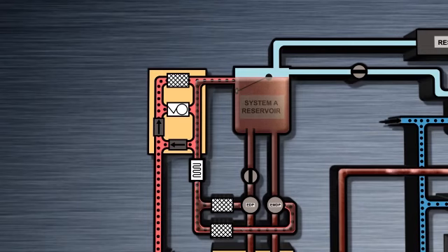Note that there are no overheat lights for the engine-driven pumps. This is because overheat situations are much less of an issue for the engine-driven pumps. The engine pumps are mechanically driven by the accessory gearbox on each engine, so the heat produced is negligible. The AC motors on the electric pumps produce a lot of heat by comparison, so the overheat warning system provides alerts to the flight crew when an overheat condition is sensed, but only for the electric pumps.